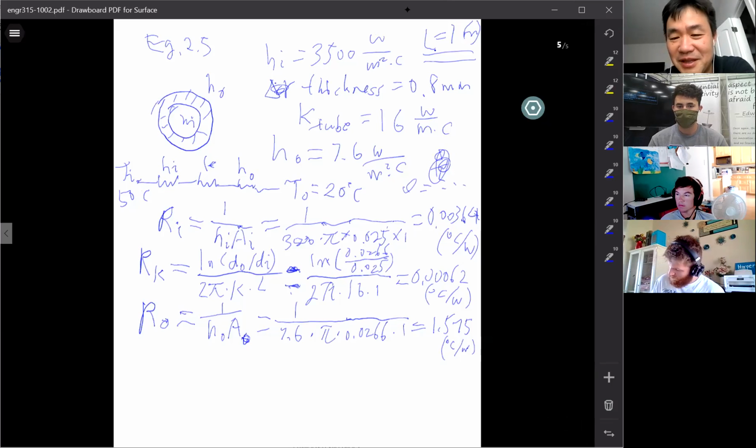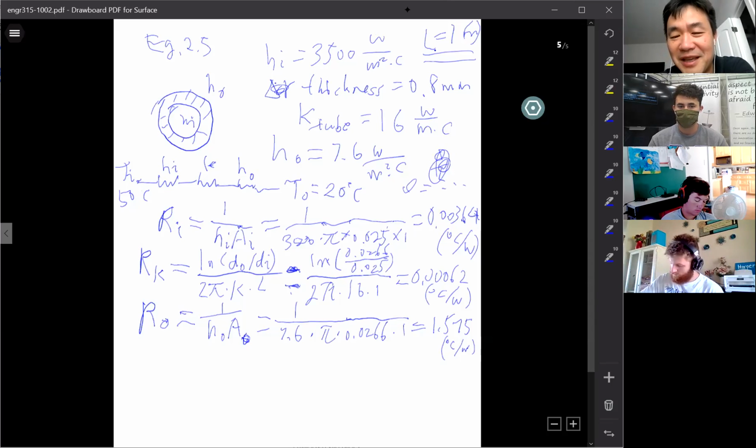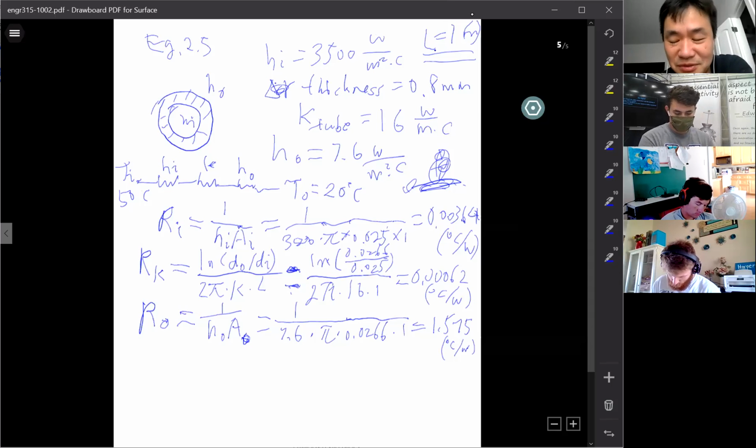Okay, so that means the equation is wrong. It's supposed to have the area in there. You didn't include the length, so it's not the real area. Okay, either you specify 1 meter here to me, or you calculate Q over L. Both of these ways are fine with me. Okay, but just don't say Q equals to something without showing the length in the equation. Okay.